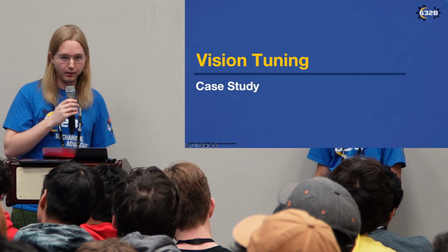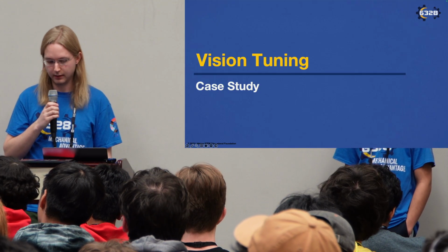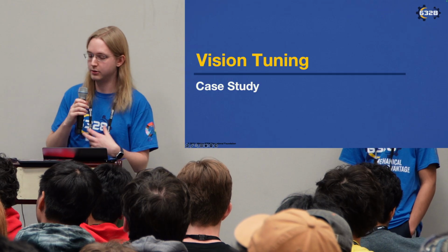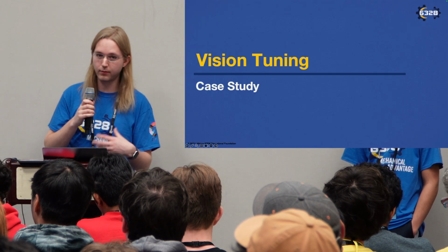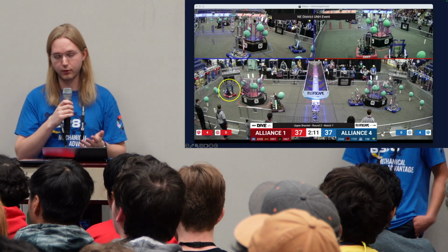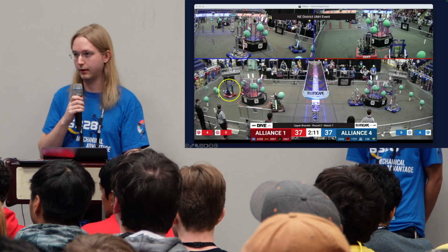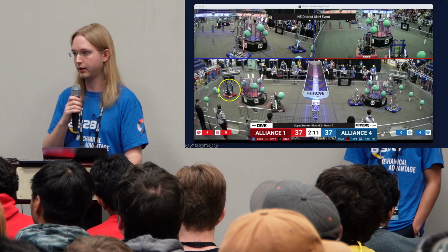Now, another common use case for modifying code in replay is vision tuning. We can change our pose estimation pipeline, which is all inside the replay bubble, and observe the new pose that we get out of this pipeline. Now, one of the features of our 2025 robot is automatic alignment for scoring in the net, which is based on localization data from the onboard cameras.